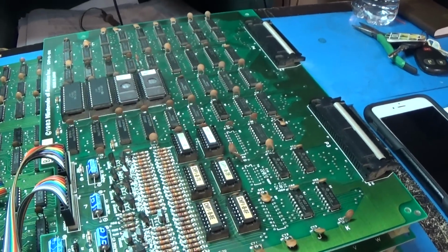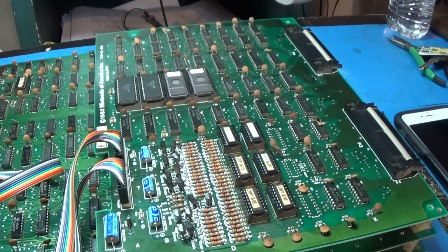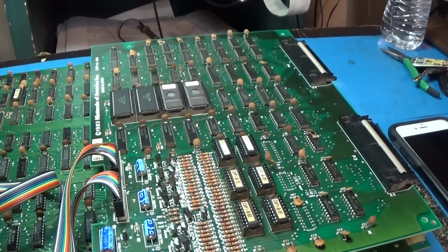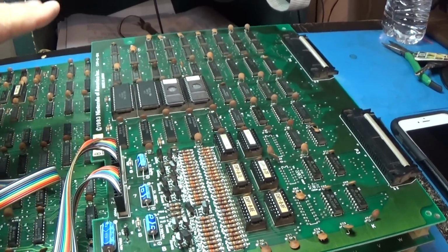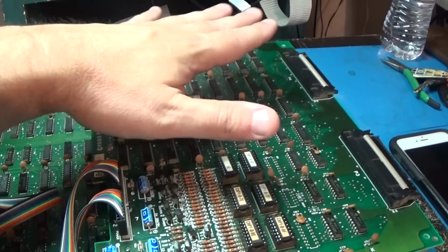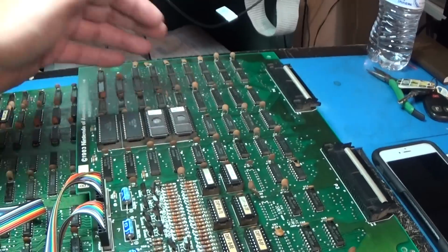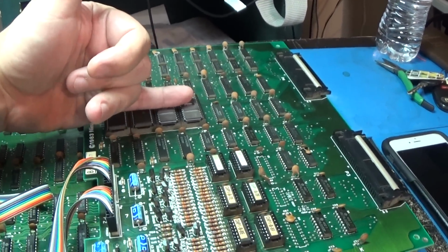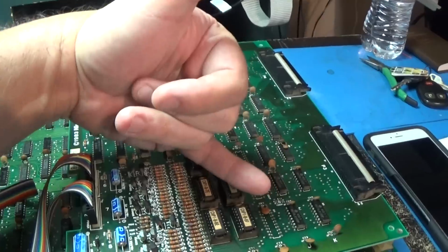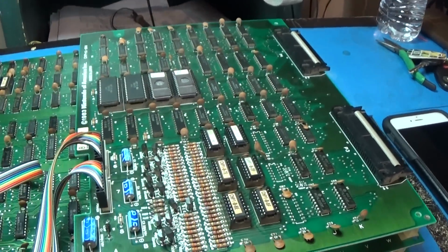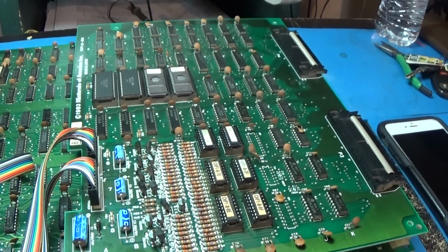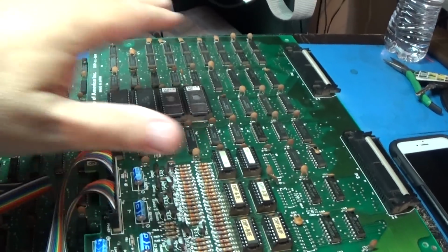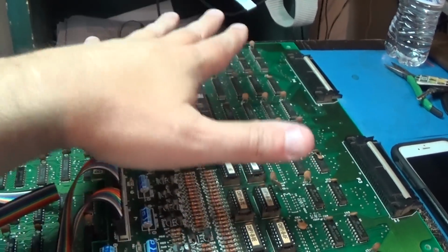That's where the problem is. So when I get back to this, I'm going to start looking at the schematic, at the read side of the RAM data. It has to address these ROMs properly, and then make its way over to these color PROMs and get pushed out to the screen. So that's what I'm going to concentrate on, the read side of things on this PCB.